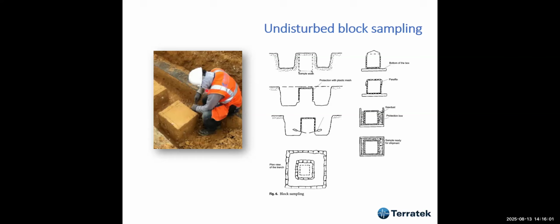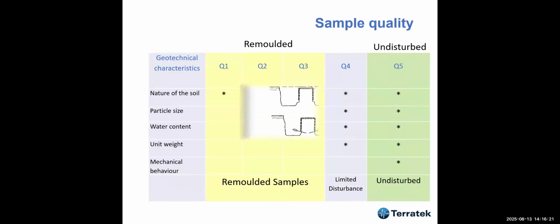Well, I have used this kind of sampling if I'm analyzing a dam and I want strength and deformation parameters for the dam. I would recommend using this. But in most cases, you cannot go very deep. You go 2-3 meters below the surface, and that's all.